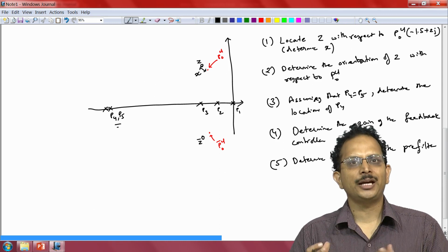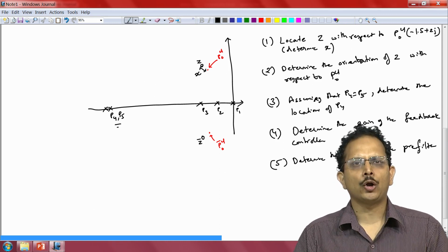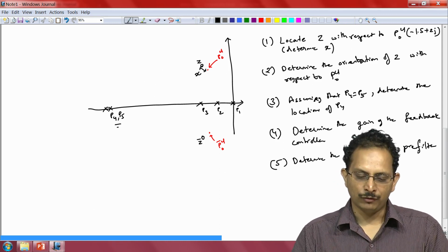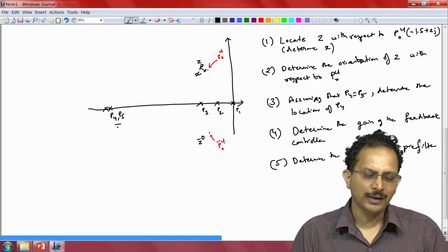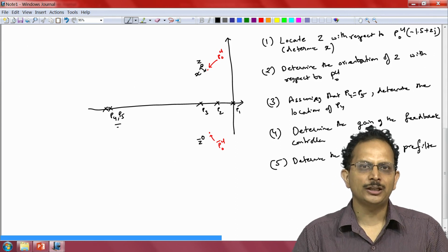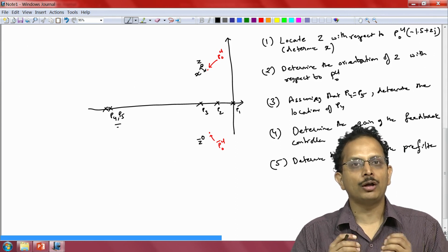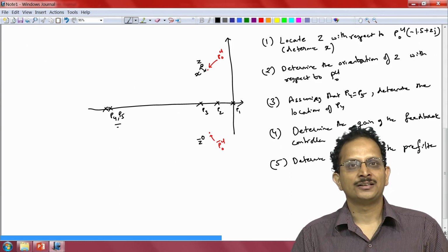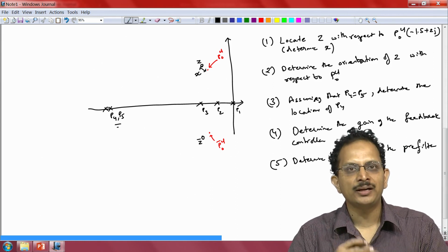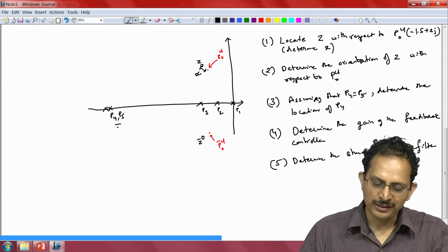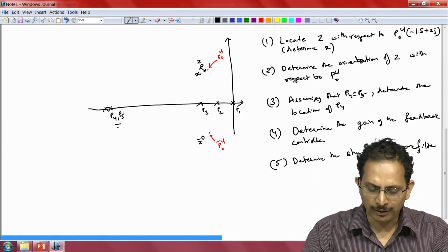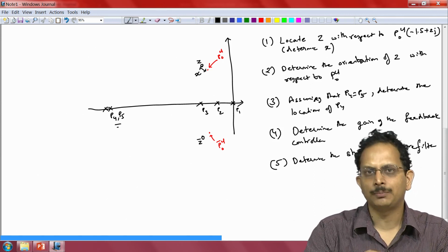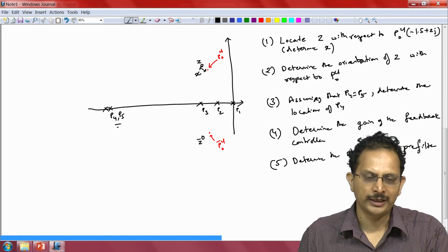Now this exact same procedure can once again be adopted without any modification for this new design as well. So even when we have this other parameter that is varying, the point PCL naught is going to be a point on the root locus, and hence the angle criterion has to be met at the point PCL naught, which means that the sum of the angles subtended at PCL naught by P1, P2, P3, Z and Z bar should add up to minus 180 degrees.